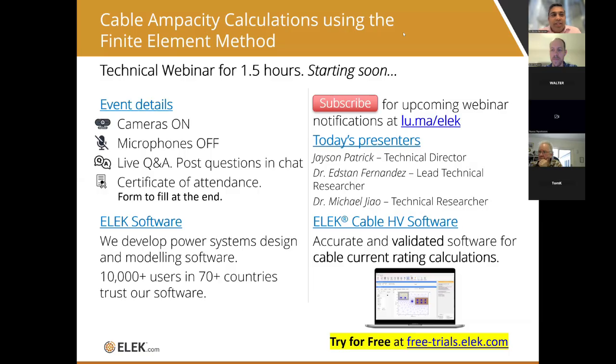The sizes of the duct are restricted between 25 to about 100 mm. There is no air convection model between the soil and the air. There's only one backfill. In addition, the duct materials are also a restriction. You could have only 5 or 6 materials like PVC, PE, concrete, all those materials. But in FEM, you can do any type of duct, any size, any duct material, etc.